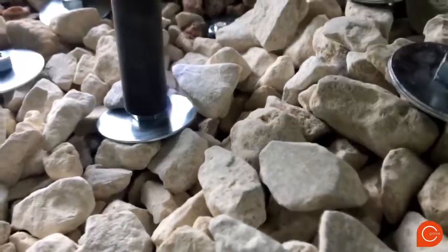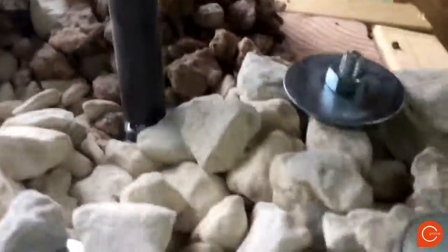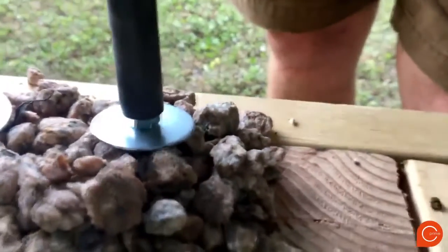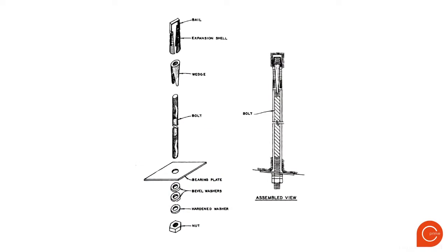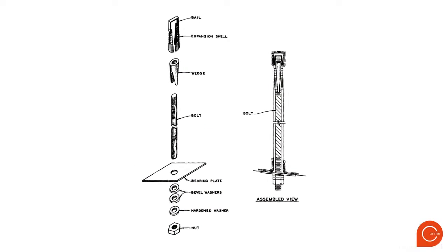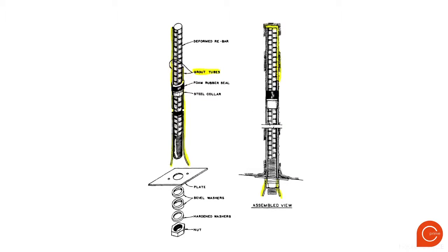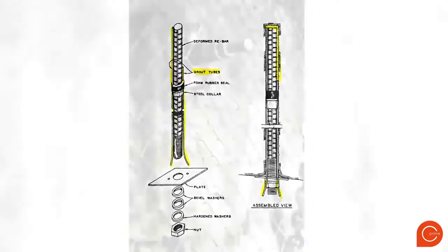To tension the rock bolts, I tighten the washers and nuts onto each one. Another obvious difference between my demo and the real world is that we don't normally have access to the top of the bolts to add nuts and washers. Instead, the rock bolts are secured at their ends by some other method. Two of the most common methods of anchoring are a wedge device and pumping in grout. It's very similar to putting an anchor in concrete or even hanging a picture frame in drywall.